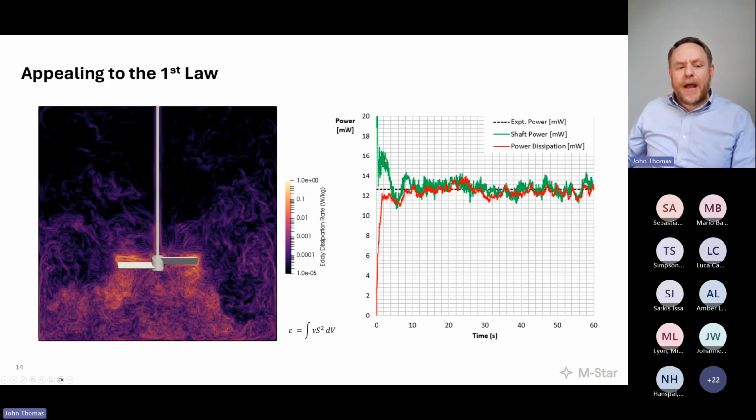Now, I've asked the question before, and I'm not going to put you on the spot, but people might say, but wait, why does power in exceed power dissipation for the first, like, 5 seconds? It should, because the fluid is accelerating, right? The kinetic energy inside the fluid is accumulating, and after maybe 20 seconds or so, we're finally at a balance where I've topped off the fluid with all the energy it needs in order to maintain some set kinetic energy, which is constant throughout the remainder of the process.